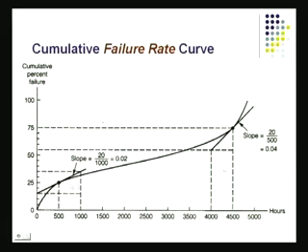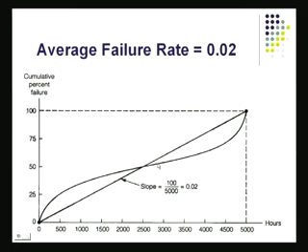And if you look at the cumulative time, the curve tends to flatten out when there is not much change in reliability over the service period. Initially there is some decay, and reliability begins to improve, and then of course as the product begins to wear out, again reliability begins to change. What we would be interested in for the most part is the service phase of the product itself. That is the part where this slope is smallest, and therefore the number of failures per unit time is also going to be smallest. This is something we would like to be able to do.